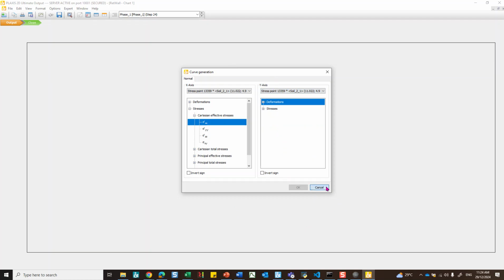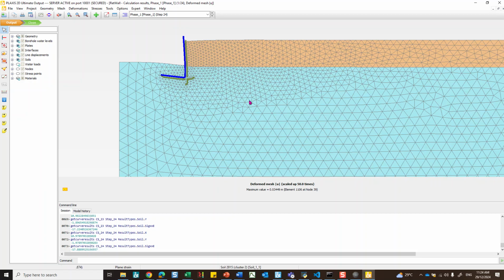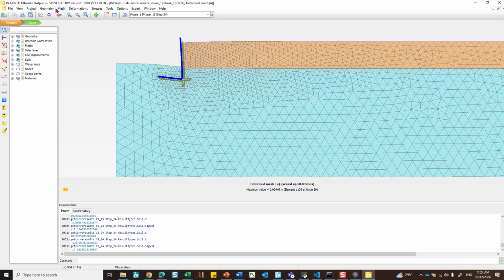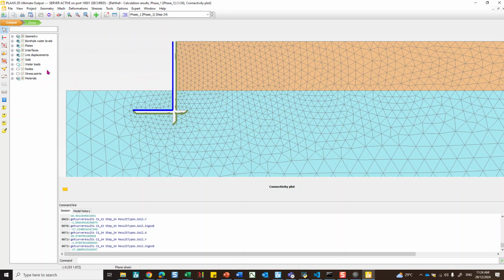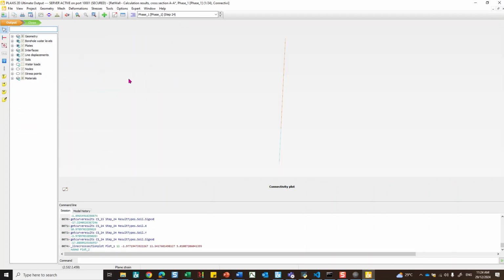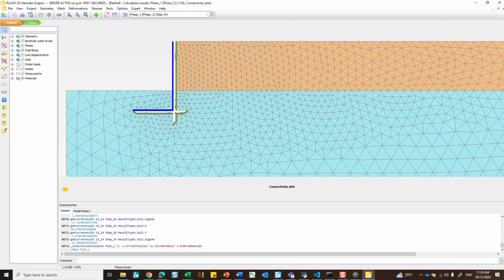Because we don't have nodal points, or we don't have actually the coordinates here, querying it by the stress point curve is not a good idea. So we go to this, and all we can do is draw the line here, and in this line we need this X to be 11. So we're getting very close. So this is 11, and I'm not sure this needs, it did not come happily, so we'll come back to this. So draw the line.